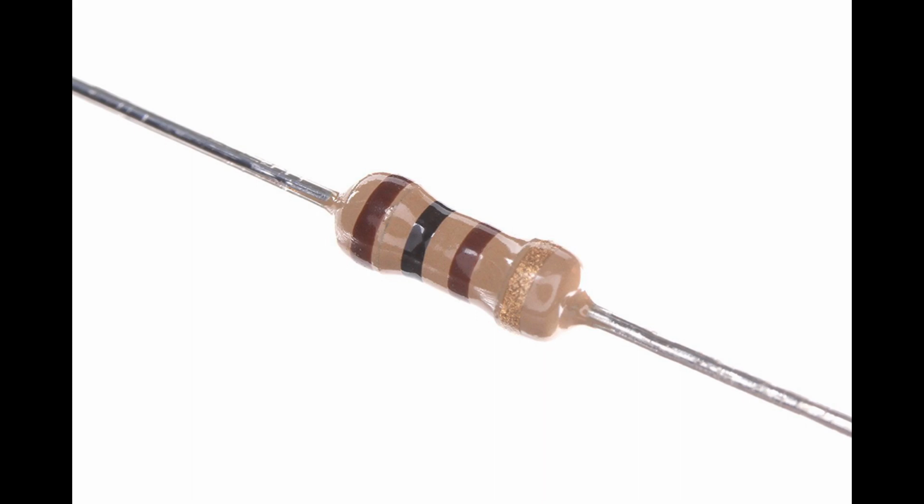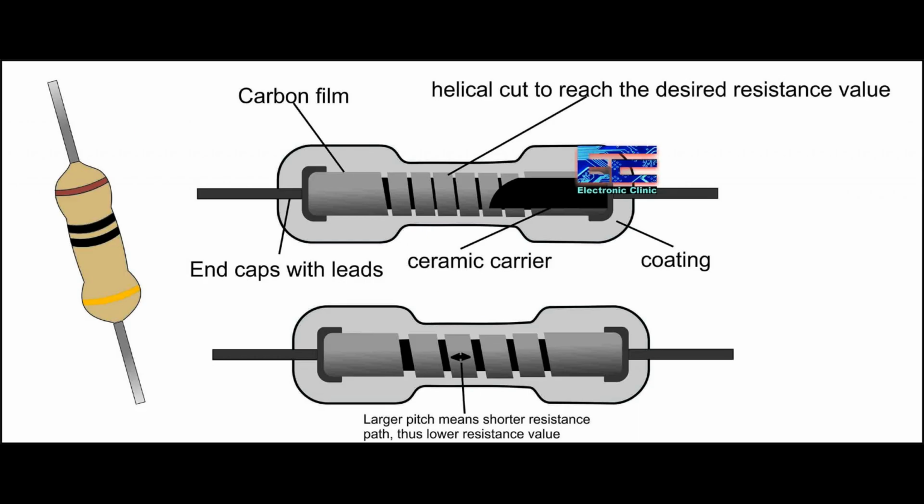Temperature coefficient. Tolerance should not be confused with the temperature coefficient, which indicates how a resistor's resistance changes with temperature. Both tolerance and temperature coefficient are important factors to consider when selecting resistors for temperature-sensitive applications. In summary, tolerance is a crucial specification when selecting resistors for electronic circuits. It determines how closely the actual resistance of the component will match the intended or nominal resistance. Engineers and designers must carefully choose resistors with tolerances that meet the required precision and performance criteria of their circuits.